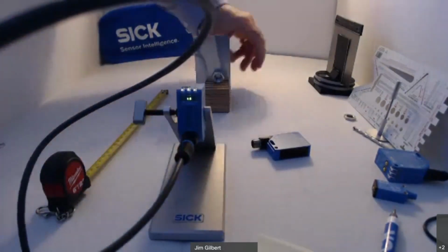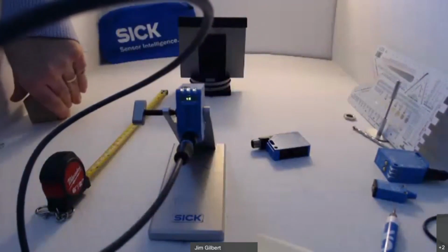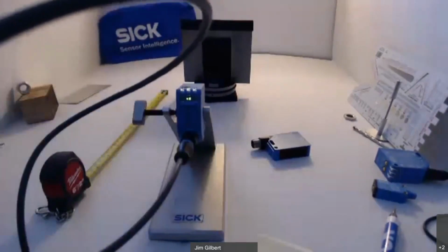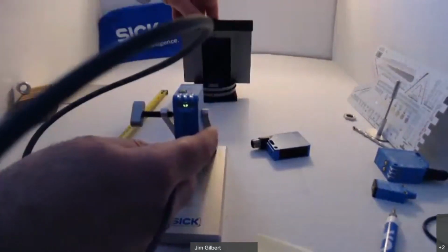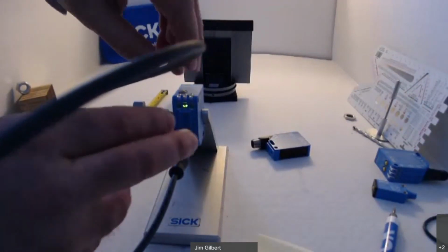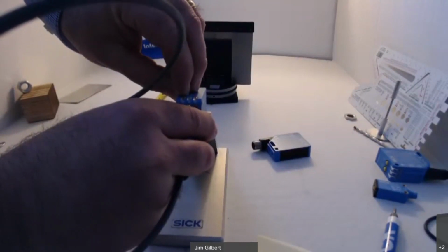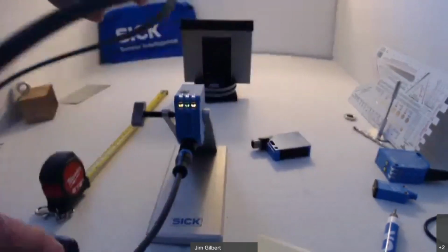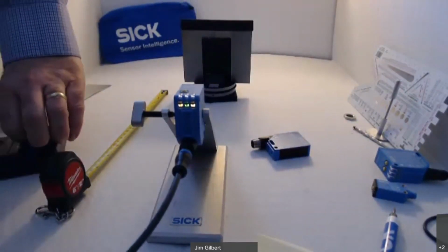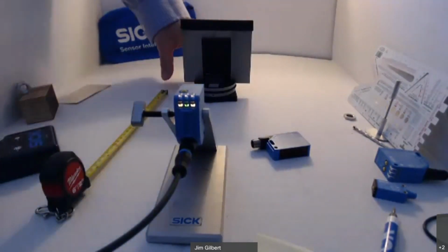Another property of these sensors: oftentimes it's not determining if a product is on another surface, but looking at a surface and trying to detect it at a steep angle. So in this case I'm going to teach it on this black matte card. The light doesn't bounce off this card very well. And I positioned it on this, essentially a protractor,